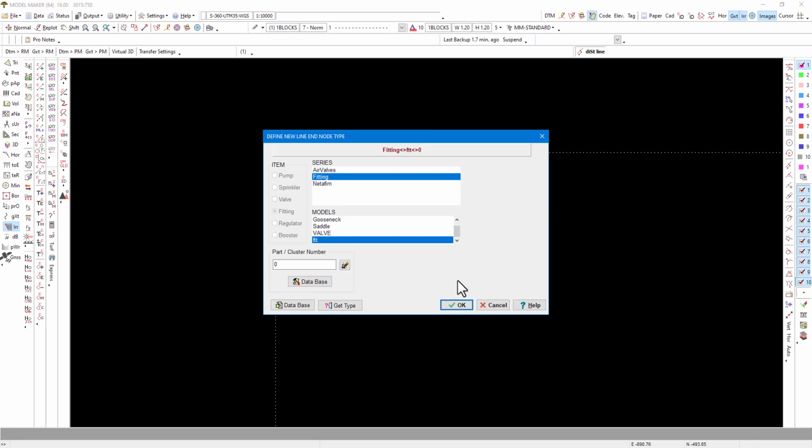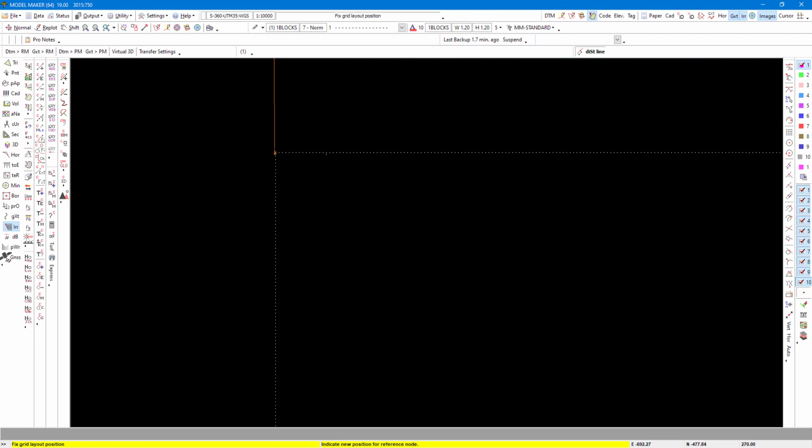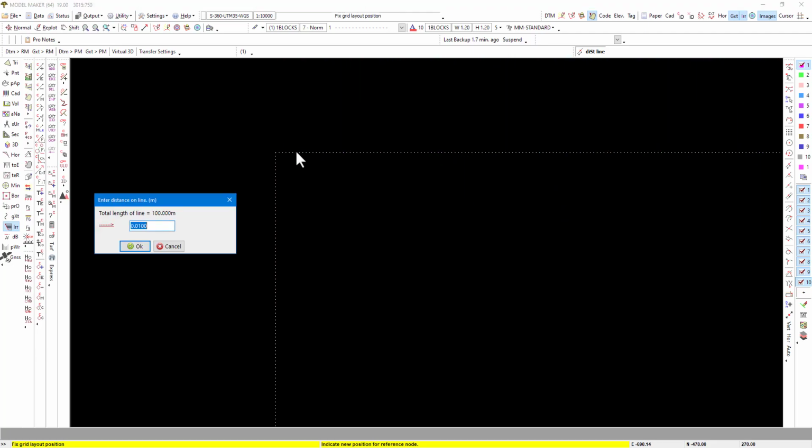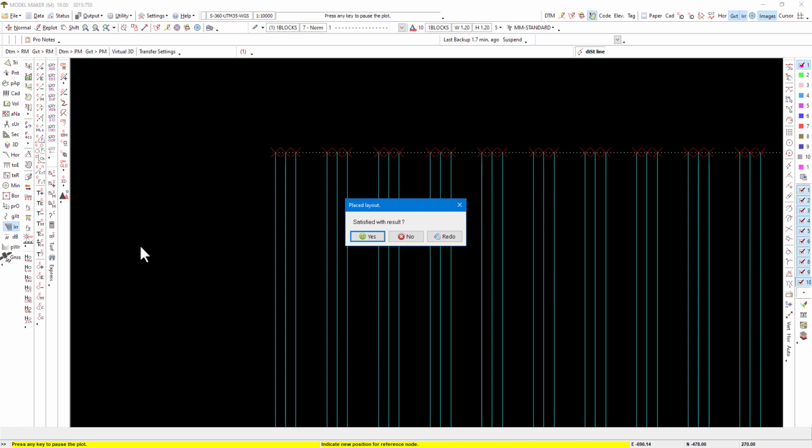Okay, in this case I'm actually going to use 1 meter because I want a line on the edge. So I have to now tell it that that first line is 1 meter away from the start of that line. And you see where the mouse is actually located right now. It sits on that middle primary lateral.